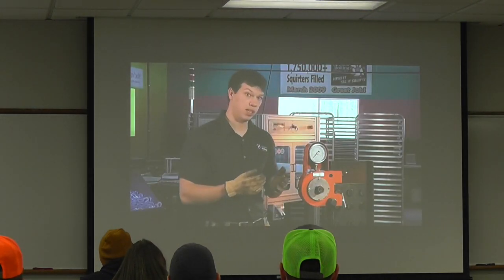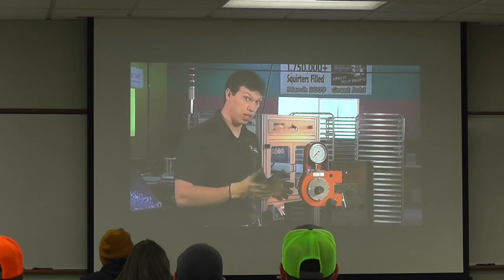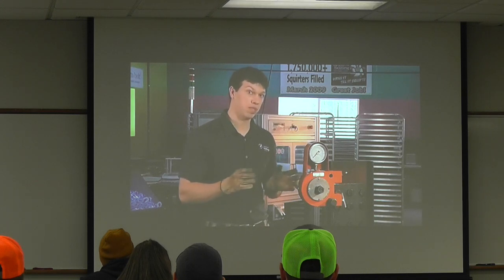Now when we do our tightening, you can either use a hand wrench, or a non-impacting hydraulic or electric gun, but for this we cannot use impact guns. So for the pre-installation verification test, no impact guns are allowed.